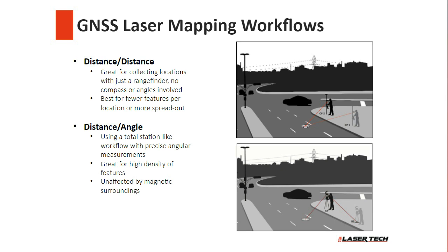So you occupy your first point, you take your distance measurement to the feature, back to the manhole in this scenario. Now you're going to be measuring distance and tilt, as Derrick mentioned earlier, so you'll get good horizontal distance for your XY or lat long location of the object, and then you'll get a good vertical distance so you can track elevation of the objects as well, or your height value.